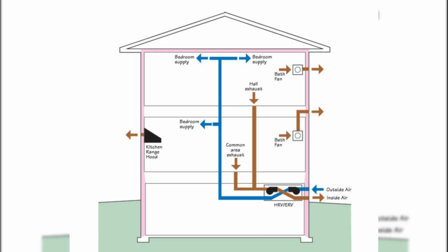and comfort. In other words, comfort is no longer about how big the equipment is. It's about how well the air is moved and mixed throughout the space. Traditional low-velocity systems just don't cut it. Instead, we need higher velocity, about 800 to 900 feet per minute, to throw the air across the room and keep temperatures even.